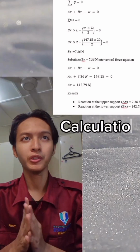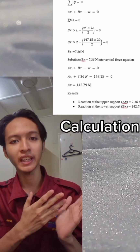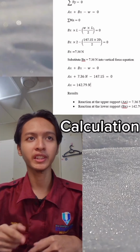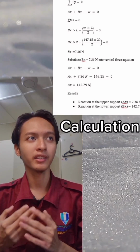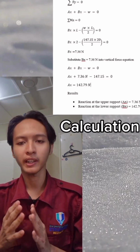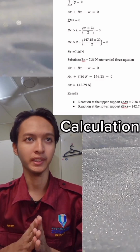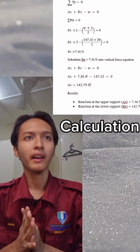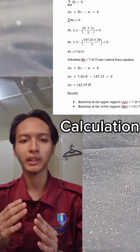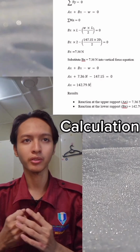Now I will show you the calculation that we use in the rigid body diagram. First, we need to convert the force acting downward, which is the weight, into Newtons. As you can see, 15 times 9.81 gives us 147.15 Newtons. Then, using the equation Ax plus Bx minus weight equal to 0, the sum of the moments also equals 0.